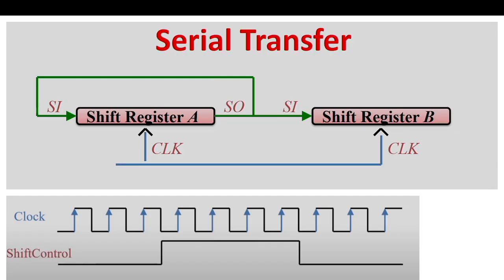So this is like a serial transfer. Here we have the rotate register. Now whenever shift control is 0, it is the retain operation, and otherwise it performs the shift operation.